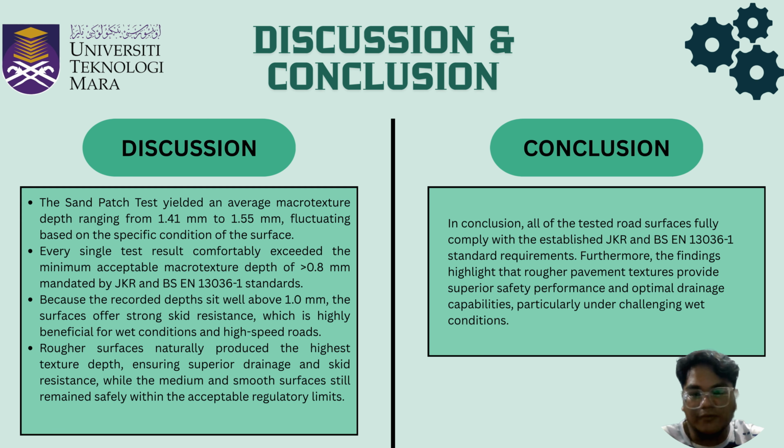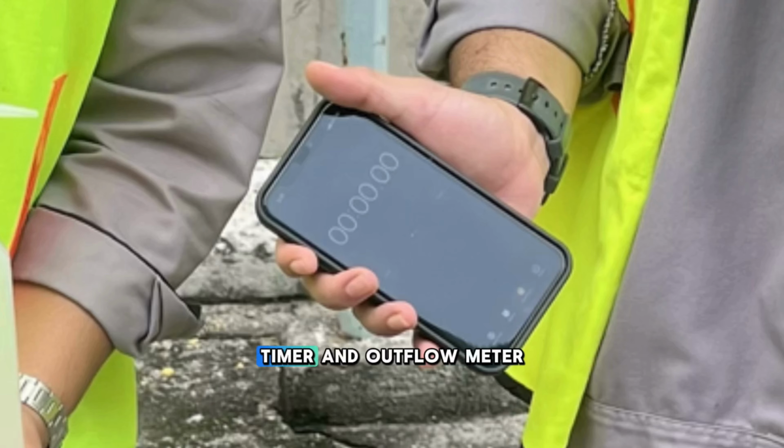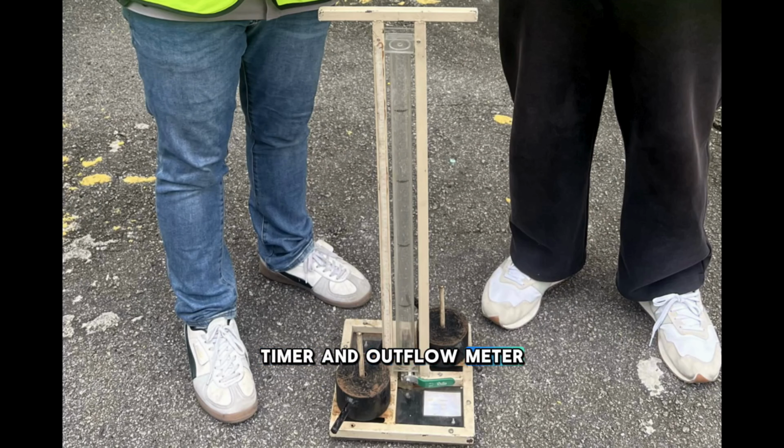Apparatus used for this test are water, timer, and outflow meter. The weight is locked to ensure stability of the outflow meter. So first, the outflow meter is placed at the first location, which is rough surface. Fill the water into the outflow meter up to 100 ml carefully to avoid spillage. Make sure eyes are perpendicular to the meter to avoid error.